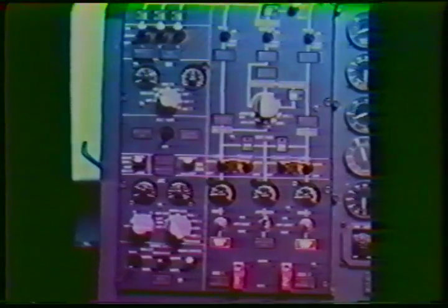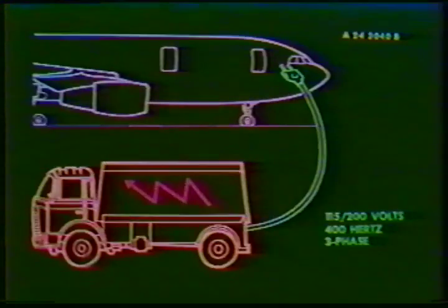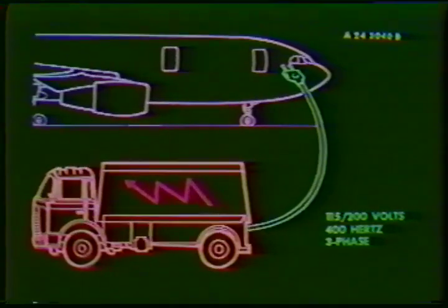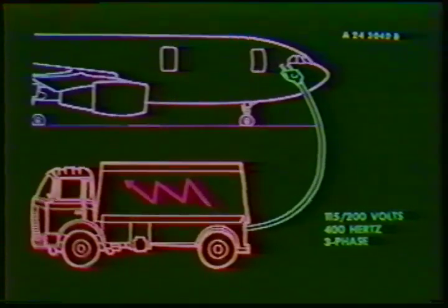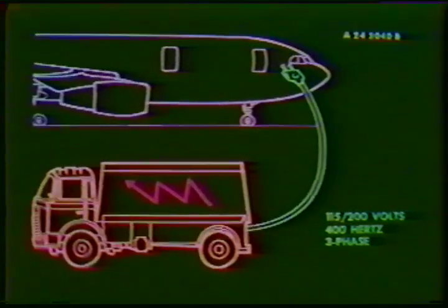Now here's a third possibility of supplying the aircraft with AC power. This can be done by an external power supply providing 115 to 200 volts, 400 hertz, 3-phase AC power. The external power supply is controlled by an external power control unit located in the main bay. When any of the listed conditions exists, the external power will not be supplied to the aircraft.